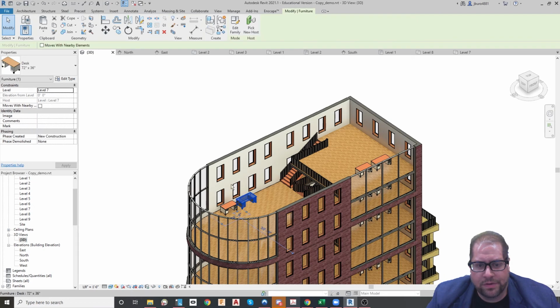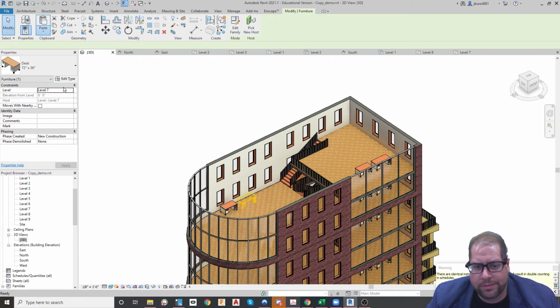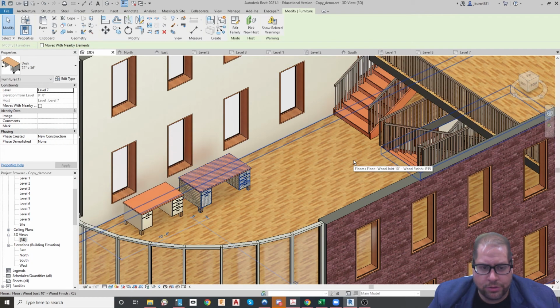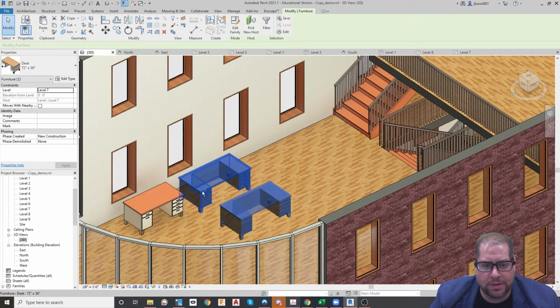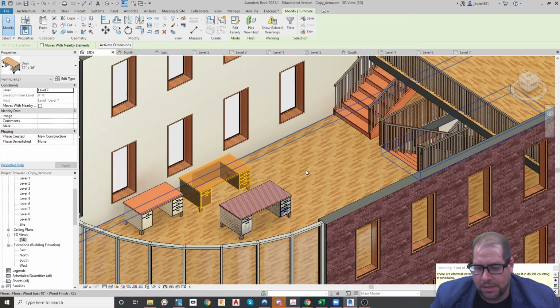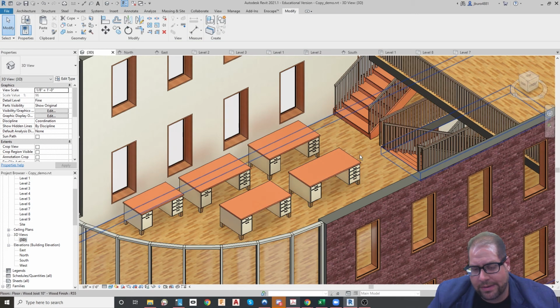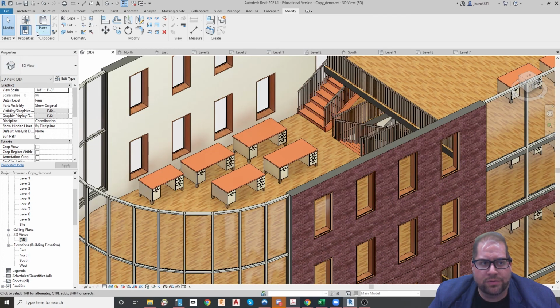There's a lot of stuff. If I pick copy again and then paste, you'll see there's other things. There's align to same place. You get a little warning when you do stuff like that because it actually makes a copy of the item in the exact same position, but you could then move it away. If you were trying to align things, you can do that really quick by just hitting copy and then paste to the same place. And again, those are warnings, but they stay selected and you can then place them very, very easily in that way. Kind of like making an array, but not really using the array tool because they stay as separate objects in that case. So that's a pretty cool feature too.